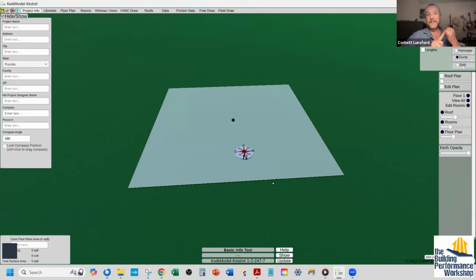I've got clients who come back to me with load calcs that they've done themselves that might need some tweaking, like, I don't know what I'm doing, I just put a bunch of numbers in here. You could use a Manual J from somebody who does just the calcs, and doing a Manual J is easy. This is really the hard part. I charge more for this duct design part because you're going to go back and forth about, can we move this here? So I'm very excited about this.